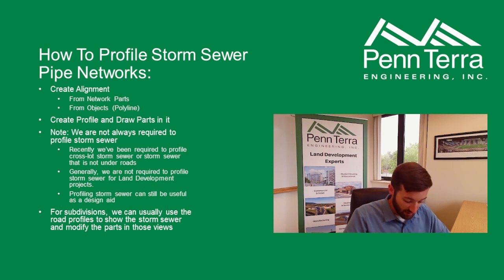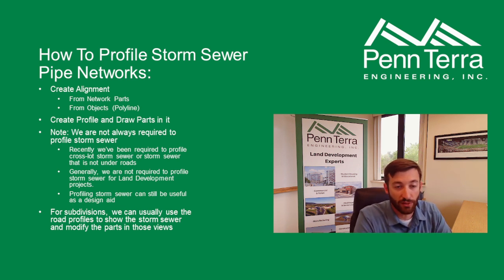So the next part of this is going to be profiling your pipe network. The first thing you want to do, just like any profile, is you need to have an alignment to make a profile view for. There's a few ways you can do this. You can do it via the network parts and it will create the alignment for you, and that requires some manipulation afterward. Or you can manually draw a polyline and create it from that, just like you would for pretty much any other alignment, like we would do for a road alignment.